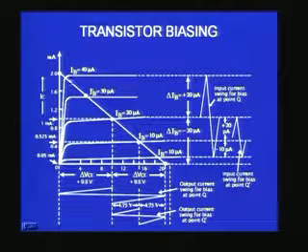And so I have shown here with the load line, if this is the biasing point, and I have a signal, for example like this, that means the signal corresponds to IB equal to 20 microamperes and it goes up to, let us say, IB equal to 40 microamperes. That means it is changing IB by nearly 20 microamperes. Similarly on the downside it can go up to this point. So this input sine wave is producing a 20 microampere plus or minus variation in the base current, and that will correspond to a corresponding change in the collector current here. You can see that, and that will correspond to a corresponding collector emitter variation here. So that is why you get a very large signal here.